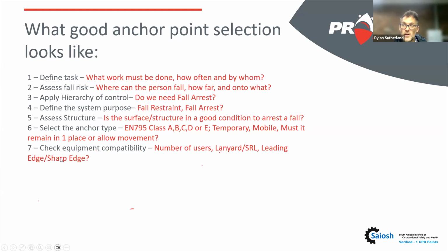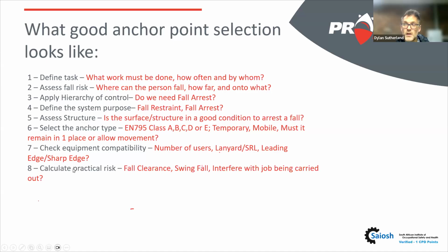Then we need to check the equipment compatibility. So is the anchor selected? Is it correct from the number of users? The lanyards and the SRLs, do we need to consider, are they using a retractable because of whatever reason? Is there other factors like leading edges and sharp edges? Unfortunately, that's a topic for itself. We'll get into that in another webinar, but that is also a critical one.